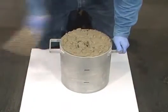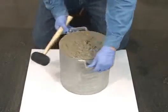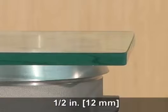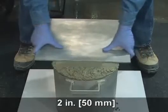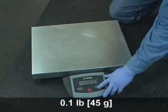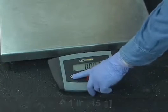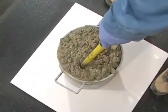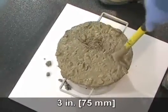The mallet is used to close voids left by the tamping rod and to release any large air bubbles trapped in the concrete. The strike-off plate can either be 1/4 inch thick metal or 1/2 inch thick glass or acrylic. The length and width of the plate must be at least 2 inches greater than the diameter of the measure. The balance or scale shall be accurate to 1/10 of a pound or to within 0.3% of the test load, whichever is greater. This standard permits the use of a mechanical vibrator to consolidate concretes having a slump of 3 inches or less.